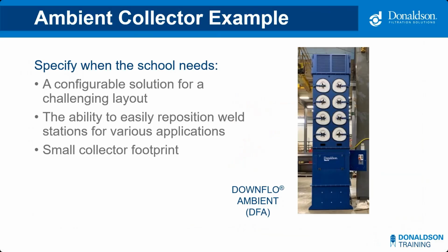Okay, so in most cases, source capture is a preferred way to control welding fumes. When equipment, layout, or obstructions make source capture impractical, ambient fume control can be an alternative. Ambient systems work by filtering air as weld fumes naturally rise toward the ceiling, reducing the overall fume concentration in the space through regular air exchanges.